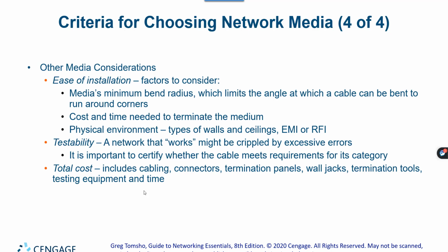You might put the wire in the wrong slot inside the connector and it won't work, and there's no way for you to know that unless you test the cable, and people start having issues and problems on their computer, and they don't tend to think about the wires in the walls when they're trying to troubleshoot. So we want to make sure we can test those wires, make sure they're not too long and that they're